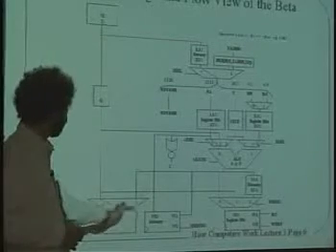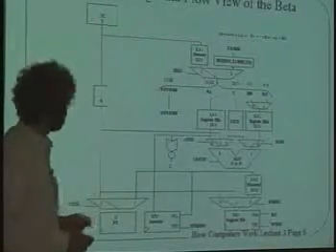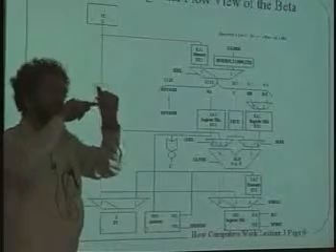So PC gets incremented by 1, gets chosen by this selector here by choosing the left-hand side, and then gets written back into the PC right here. And that's how we increment the PC. Most textbooks will show you this drawn with these two boxes as one box and a loop showing you PC gets PC + 1 and a loop going back to the top.